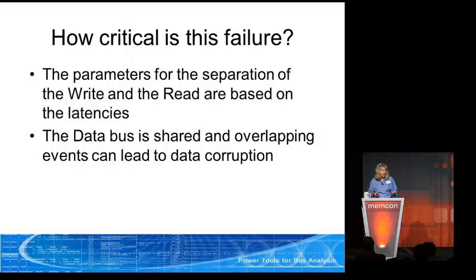And actually, we were at a customer site, in Shenzhen last spring, where we had a customer that had some very rigorous test software. It was exercising the system, and it crashed. We did this exact analysis. We worked backwards, and it was a read too close to an activate. These types of things would not occur in this particular system unless there was a lot of traffic going on, a lot of events. So all of these events combined created the statistical probability that the read was too close to the activate.